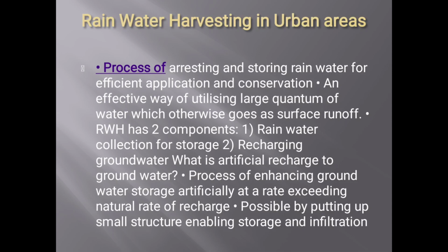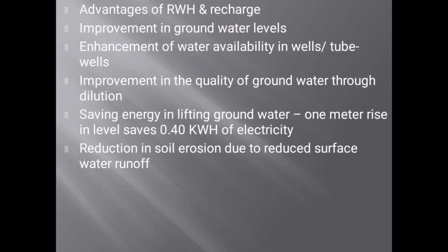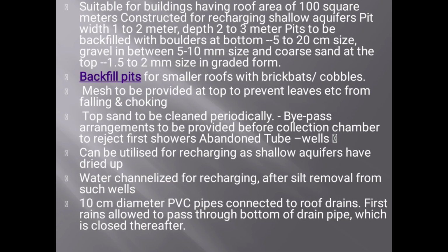Again, there are two components as we know: rainwater harvesting for storage and recharging of groundwater. It is the process of enhancing groundwater storage artificially above the existing natural rate of recharge, possibly by putting up a small structure allowing storage and infiltration. These are the advantages: improved groundwater level, enhanced water availability, improved quality of groundwater through dilution, savings of energy, reduction in soil erosion, etc.